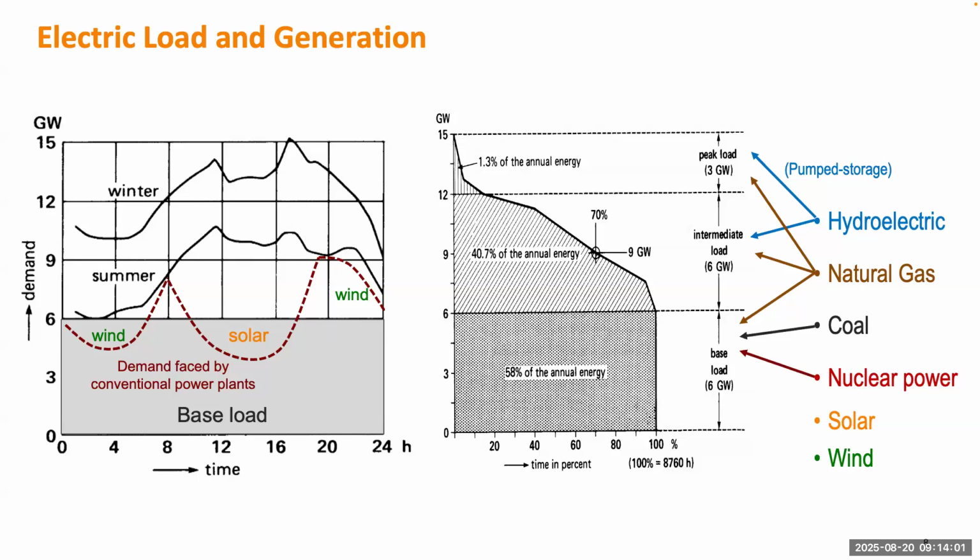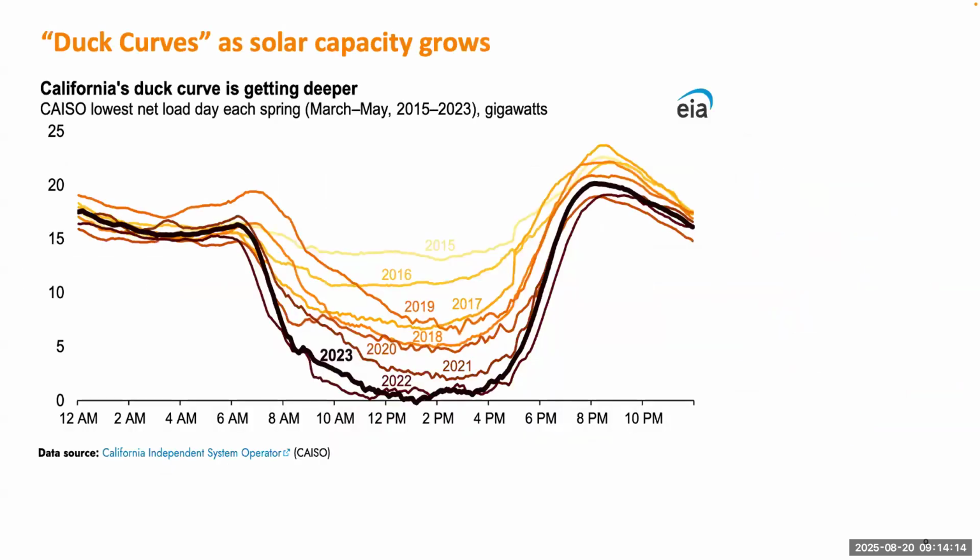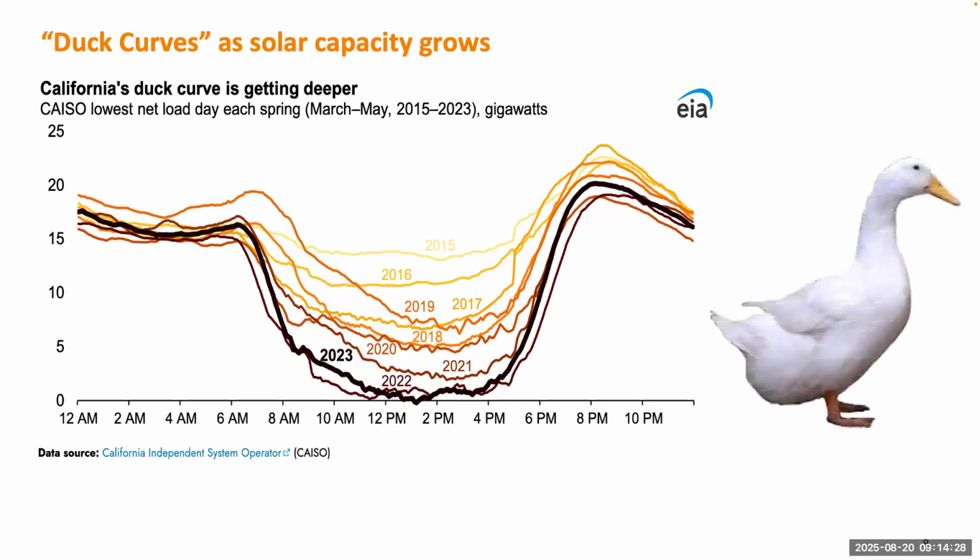And in the evening or early morning, we can utilize the wind to power the load. That will largely change the load curve and cause this duck curve. The duck curve will be very different from a conventional load curve over 24 hours. So there will be more reliability challenges because you want to balance the load in real time.